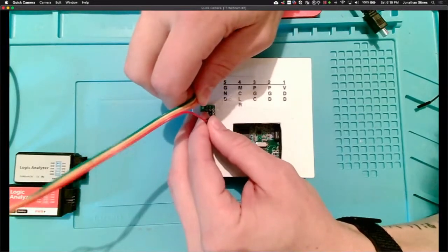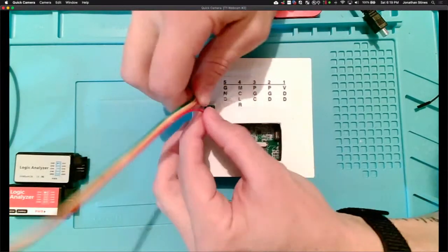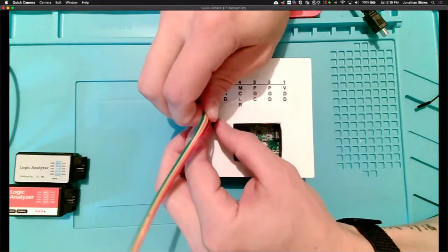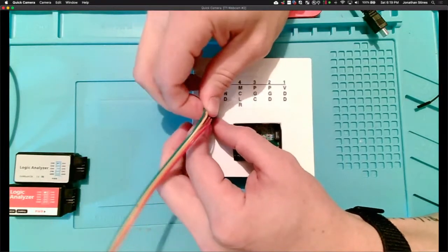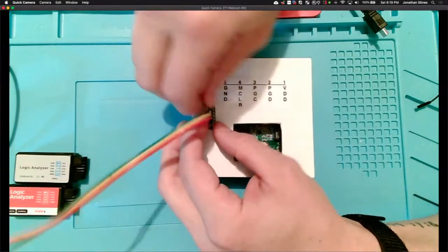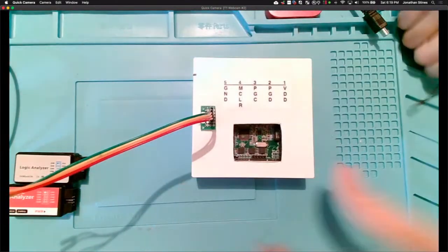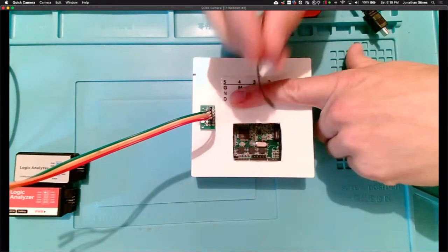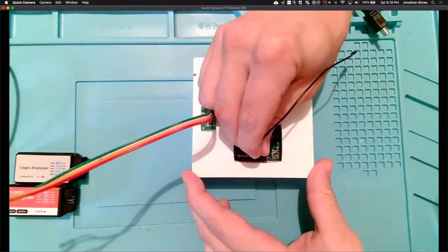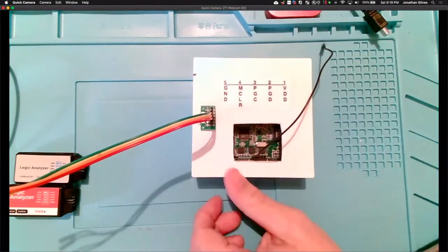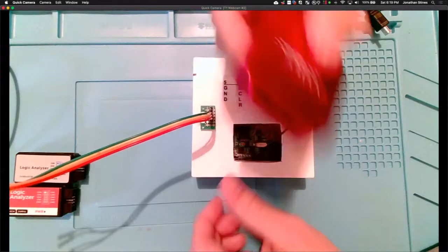For doing SPI, particularly if you only have one slave connecting to master, you actually only need to connect master out, slave in, and clock in order to facilitate that connection. But just for the fun of it, let's just connect them all. Also, I'm going to mooch off the ground interface of this ICSP down here, just to have something. So anyways, very similar to what we saw with the other ones.